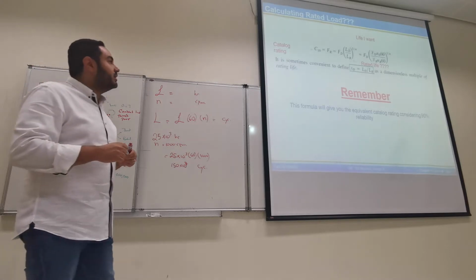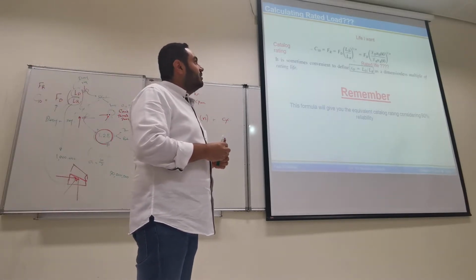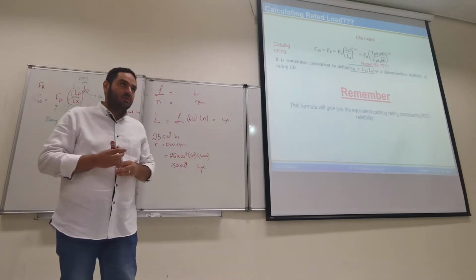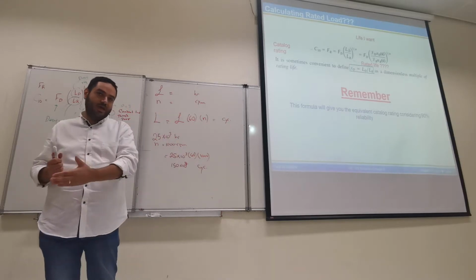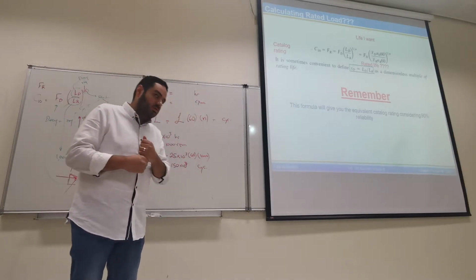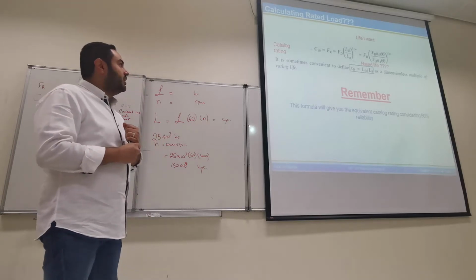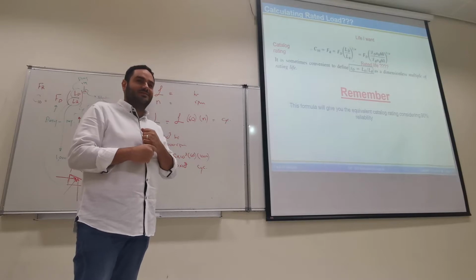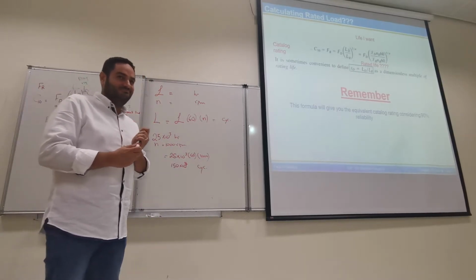The catalog rating is the maximum, right? The catalog rating is the capacity of the bearing. I will not say maximum because it is based on certain tests, but the conditions you have are different. Under this specified test, if it exceeds that, it would fail. It will indicate a 90% passing bearing. So under the same load, 10% have failed already.